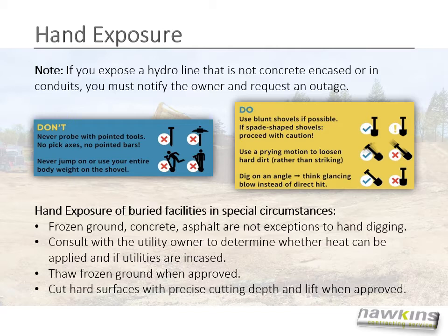Hand exposure of buried facilities can occur in special circumstances. Frozen ground, concrete, and asphalt are not exceptions to hand digging. You need to consult with the utility owner to determine whether heat can be applied and if utilities are encased. Then thaw frozen ground when approved, and cut hard surfaces with precise cutting depth and lift only when approved.